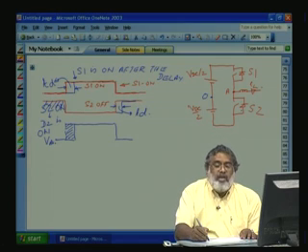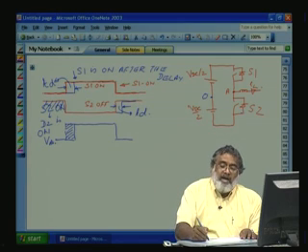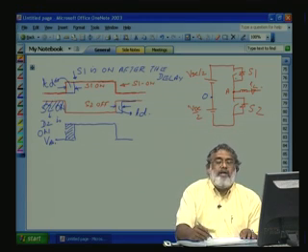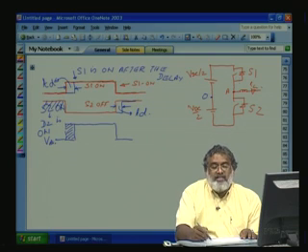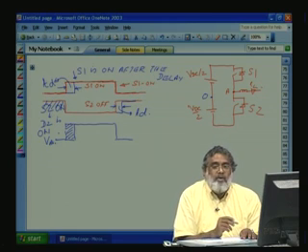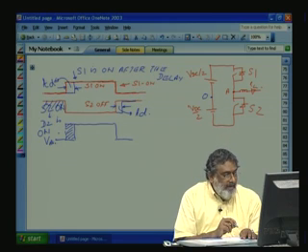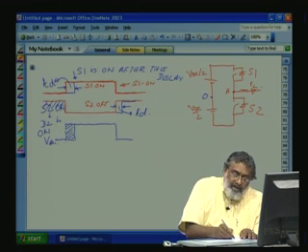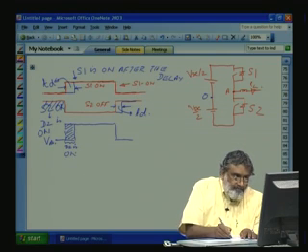But whenever the diode is conducting, the conductions are instantaneous, so that time even the dead time will not have an effect. But whenever the active switching device, the transistor, conducts instead of the diode, because of the delay this much area is lost. Till this period D2 will be conducting, D2 is on.